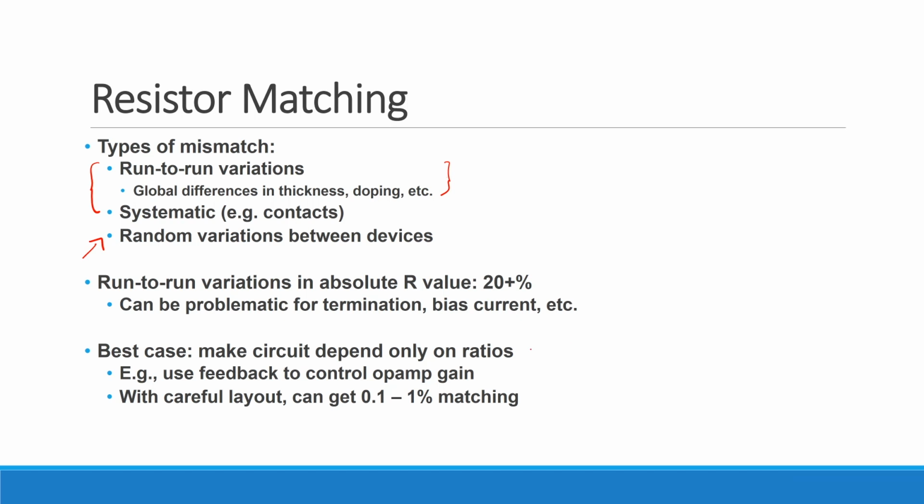So that's why, again, if you really look at analog circuits, and in particular why CMOS circuits have actually eventually been successful, it's because people figured out how to make sure that they made their circuits only depend on ratios of otherwise identical things. Okay? If you make it based on ratios, you can do extremely well with CMOS. Okay, and I gave some numbers here, anywhere from like, let's say 0.1 to 1% matching. In fact, you can even do better than that. Okay, so just to give you some idea, that's about 10, 12, 13 bits kind of resolution that you can get just based on doing that kind of matching.